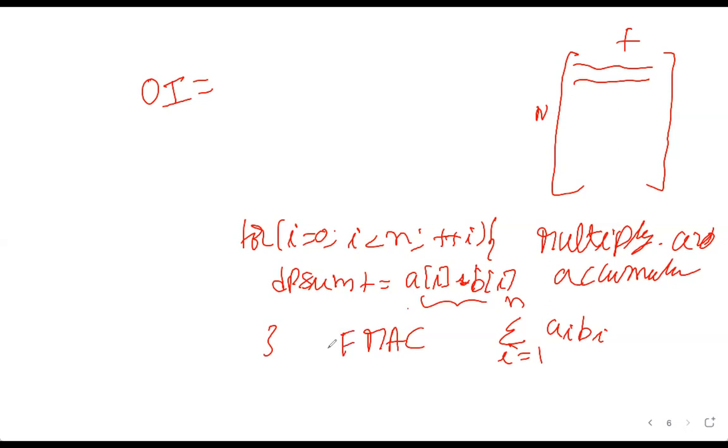In fact, DSPs are specially designed for floating point multiply and accumulate operations, or FMAC. In any case, you perform one multiplication and one addition. So as part of querying, for every dot product between the query vector and a row, you perform 2v operations, where v is the dimension. Since we have n such rows, we have n into 2v.